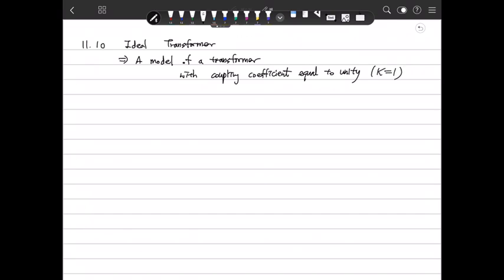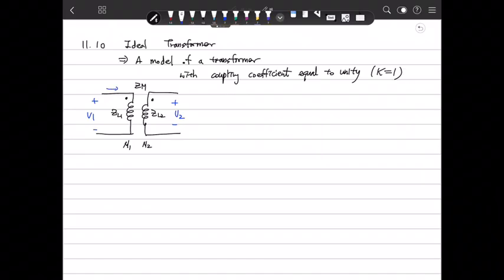So I already showed you that. Actually, this is a coupled inductor here. We define the turn numbers as N1 and N2, and the mutual impedance is jωM. This is jωL1, jωL2, and you can define the voltages here: V1 and V2. Then the currents are I1 and I2.